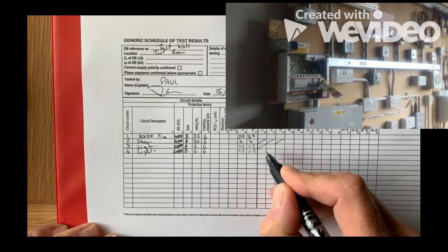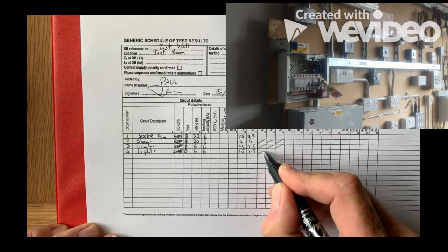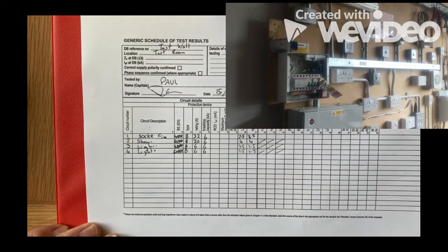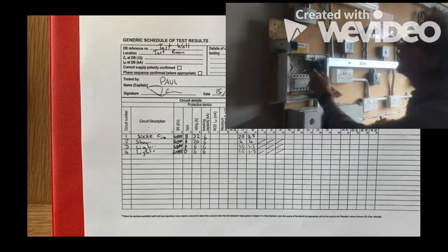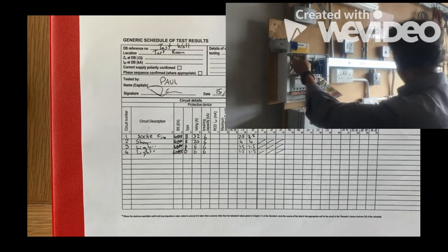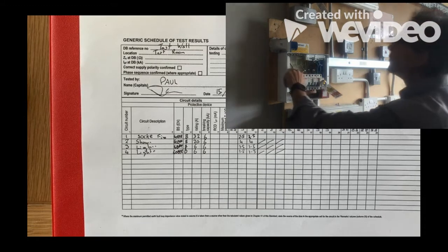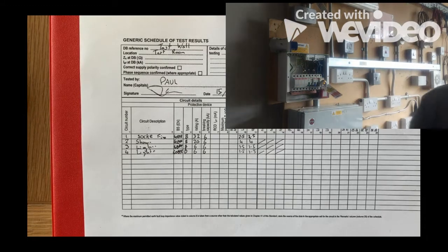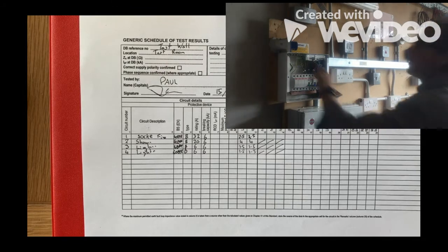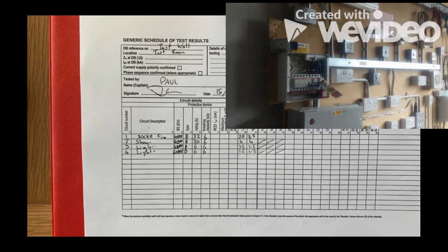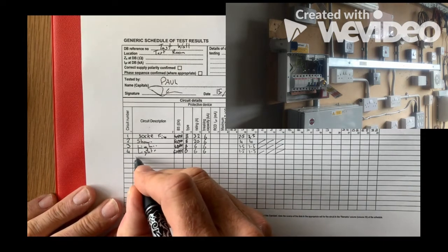The same for the lighting. So we can do this. So we can do that. I'll just check and see if there's any bonding on this circuit. 1, 2, 3. There's no bonding on this one at the moment. We'll have a look at the bonding. There is actually a bonding circuit, so I'm going to add that down here as well, and that is for the water pipe. So we're just going to put water pipe here.